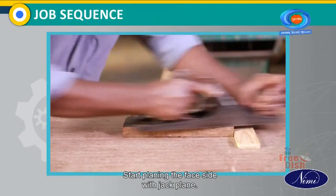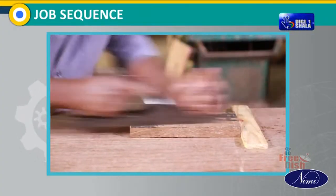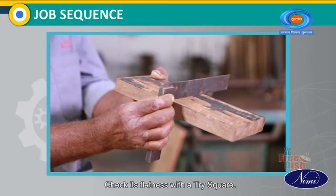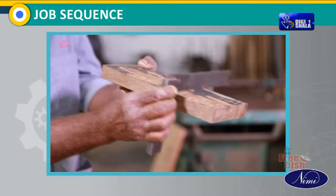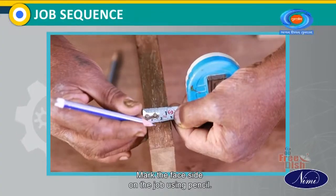Start planing the face side with jack plane. Check its flatness with a tri-square. Mark the face side on the job using pencil.